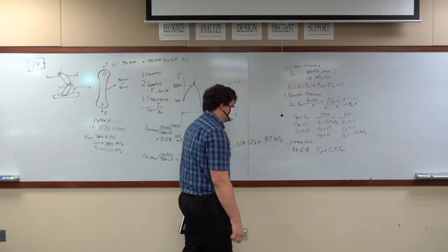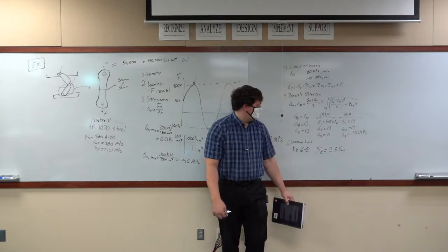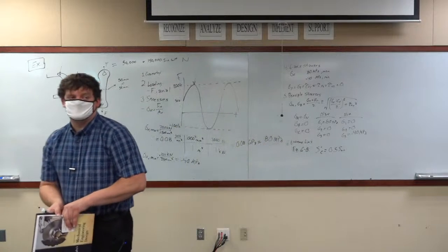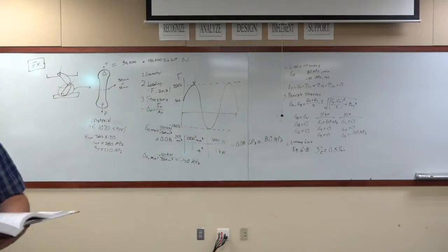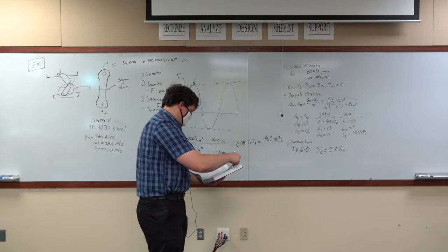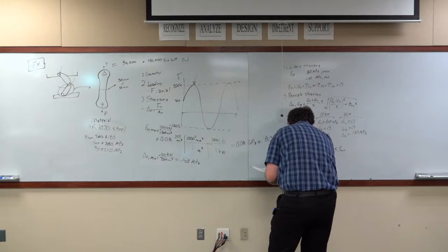It's the nominal endurance limit. This is our best estimate that we start with. Okay? The goal is we start with this value and then we modify it based on our loading conditions, based on our material choice, based on everything. So we're going to take, after this, equation 6.18.